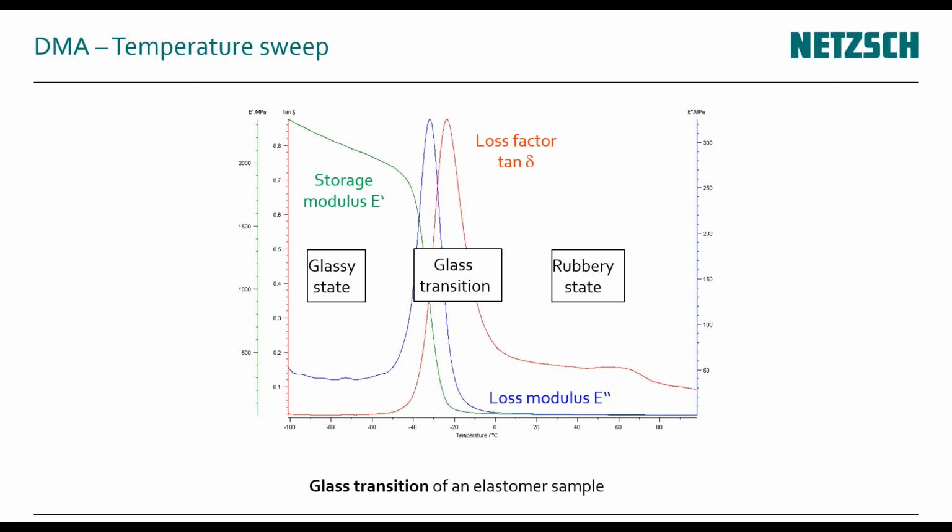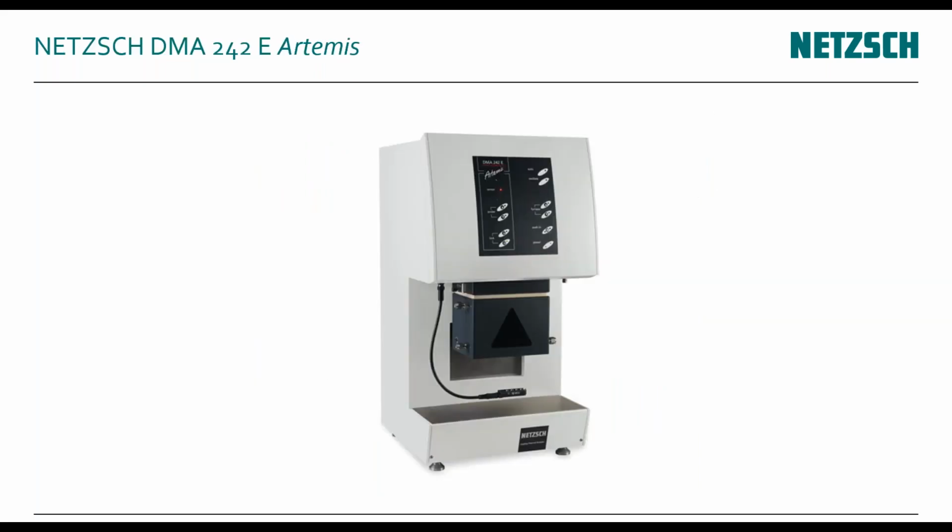And you see the glass transition, and it's a transition region. And above that, we're in the rubbery state. So you can already see two things. Glass transition is a transition region. There's no way that the polymer can just switch. And the second thing, of course, this is just the same picture for a composite material, as we will see in a second, but the glass transition is very much shifted to another region.